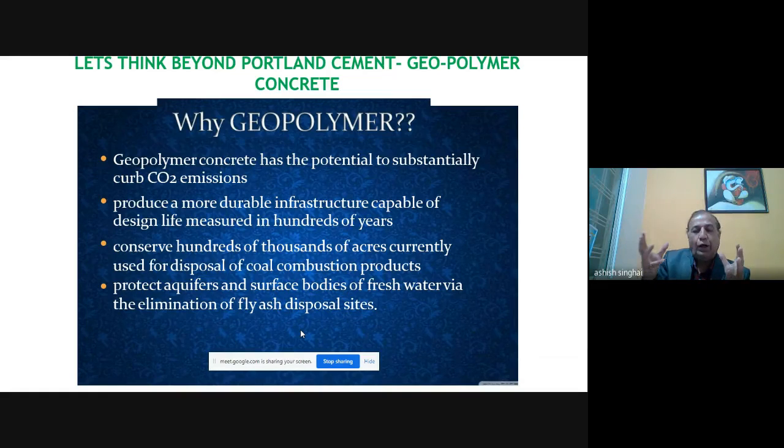We are using almost 50 to 60% of the fly ash plus some activators in the form of sodium hydroxide and calcium hydroxides. They react with each other chemically, form a gel at a very elevated temperature, and after the gelification and geopolymerization, the material is so produced, and we add, obviously, aggregates also, normal aggregates.